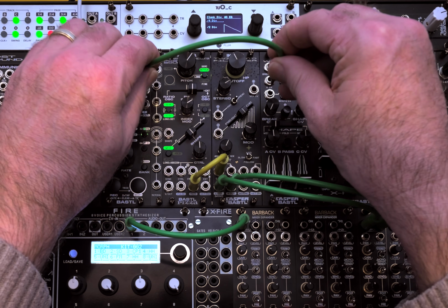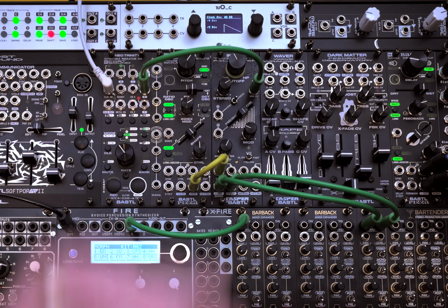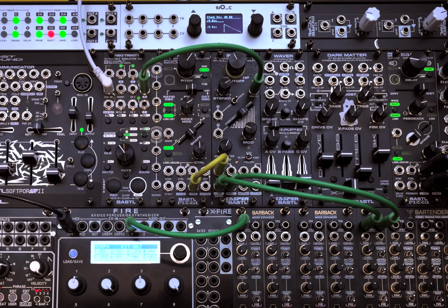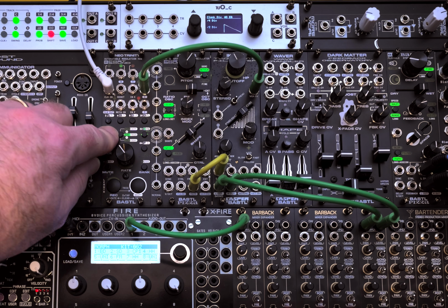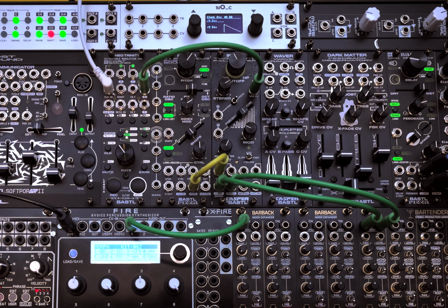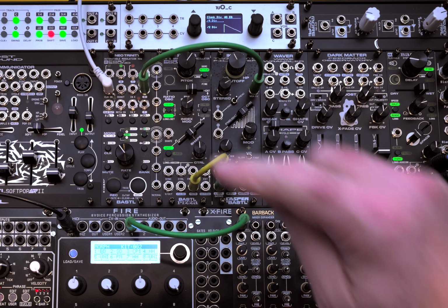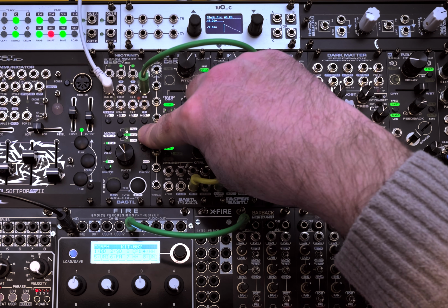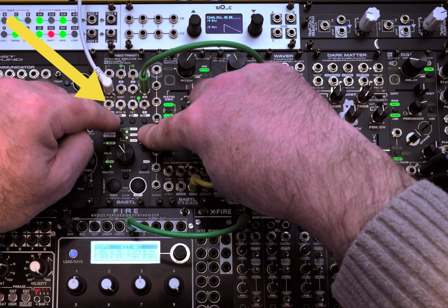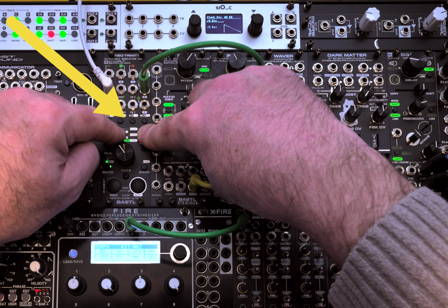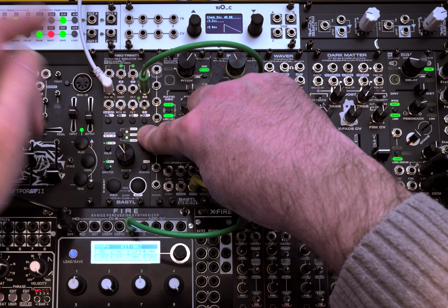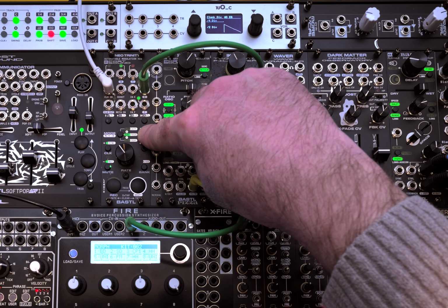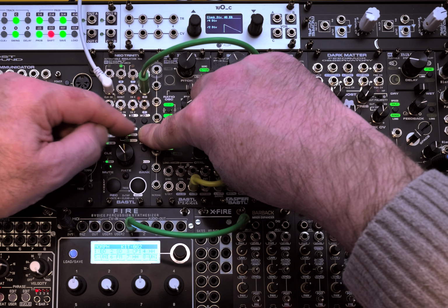Let's just patch output E here into the VCA of Ikarie. And we're going to go over here onto channel E, we're going to set it to envelope mode, which is what we were using previously. But now we need to configure input E. And the inputs are configured by pressing and holding the channel button and then using this mode button to cycle through different LED combinations here, which correspond to different ways that that voltage or trigger is interpreted. So for this particular case, we want it on env trigger, envelope trigger mode.